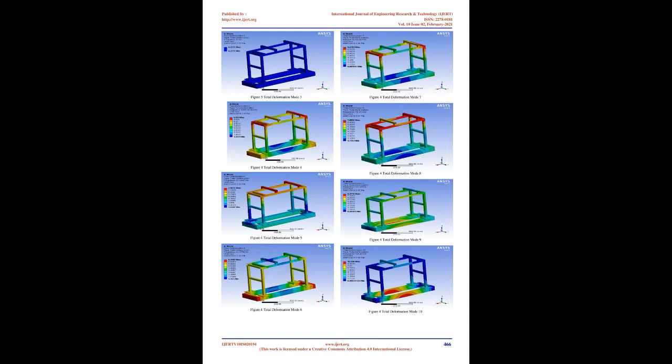A 3-jaw chuck for a drilling machine is the device which is used to hold objects of a circular cross-section. As we have selected the topic to clean the internal pipe, we have only one option, that we have to select a chuck. Chuck is already available in the market. It is very easy to hold an object in it and also easy to mount and rotate it on a motor. Size of chuck equals 1.5 to 13 mm standard, weight equals 0.400 kilograms.